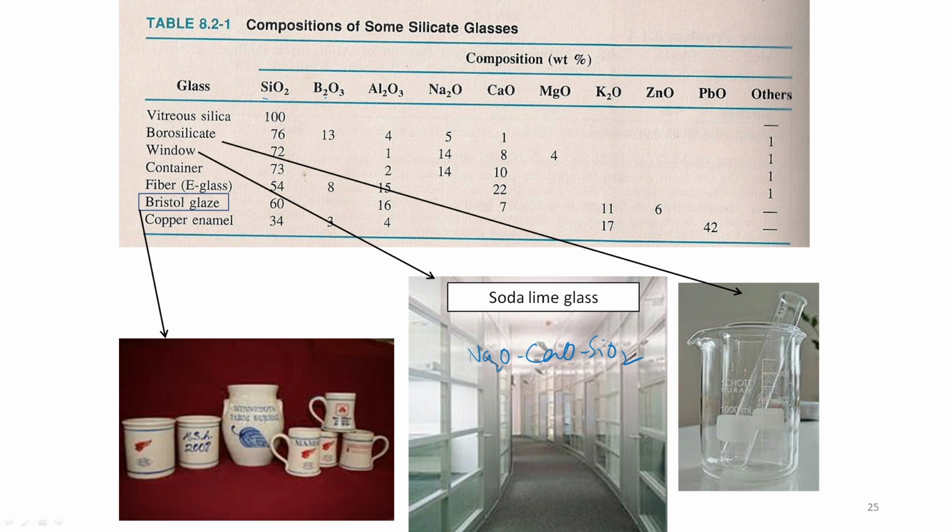Many of the glasses on car windows are toughened glasses. They have a little bit of K2O. This K, a potassium ion, which is bigger than sodium ions, replaces some of the sodium ions and creates a surface compressive stress, and that makes it tough so that it does not break. Please go back to the discussion on toughness, how toughness is defined. So, tough glasses are very important. Even if you give a punch to the glass, it will not break. So, that is about the glasses and other things.